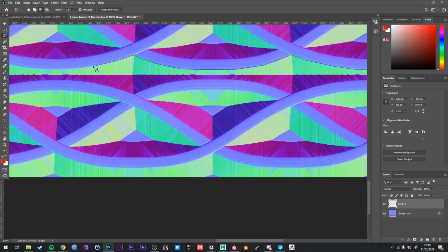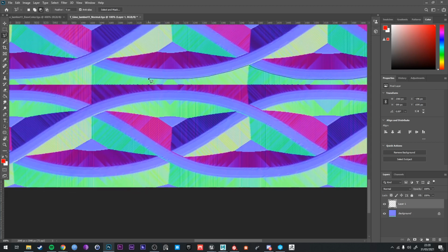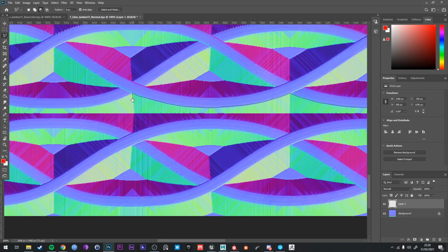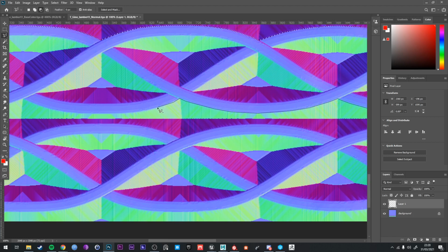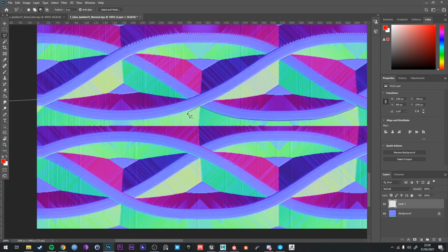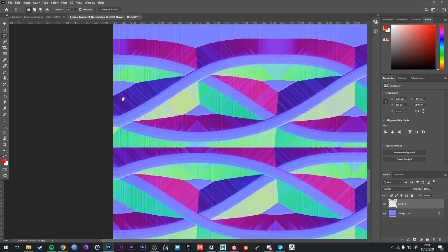So why did I pick the normal map for this? Literally just because it had the clearest transition between the parts that are meant to be opaque and the parts that are meant to be transparent in terms of its color. The base color was very hard to tell because of what we call dilation. So you can see some dilation here, how the colors are bleeding out from the edges. And this is something that Substance Painter does to compensate for errors you might see in 3D when your textures are getting lodded or level of detail compressed down.